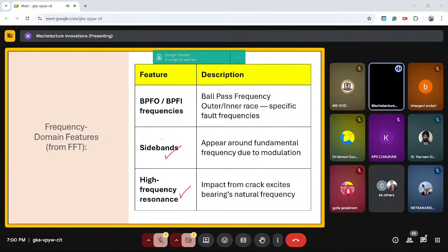It's not only one data, two data. All the time domain data and all the frequency domain data are instantaneously calculated for a given duration of the window to come to a conclusion that this system has a crack. Okay, so you can understand from this simple example, the AI predicts a crack not from one data, but by using various combinations of the data, and all the data are collectively calculated and studied on their pattern to say what the failure is. Okay, when all the data increase, it means a crack. There are cases for other failures where some data might increase, but some other data might decrease. So you need to know what increases, what decreases, the pattern. If you understand, it can detect the failure.